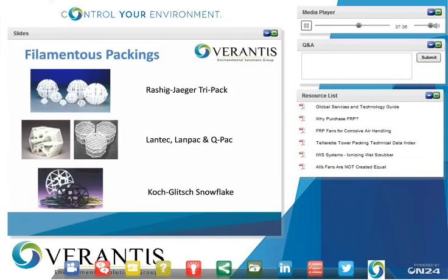Filamentous packings, that's really the most current style of packings that are used in most applications for scrubbing. They've been developed over the years to try to minimize pressure drop, which correlates to energy usage. Everyone is always trying to minimize the amount of power that they use and energy costs, and at the same time improve mass transfer to get higher efficiency removals, because again, over the years what has occurred is the regulatory requirements have gotten stricter and stricter, where people are trying to get much higher efficiencies in their scrubbers.